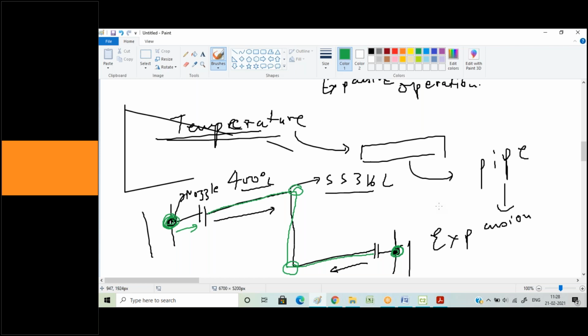There is no such thing there. For example, how much do you have to maintain the sustained sag? Because obviously, in the sustained condition, if I am doing stress analysis, first I want to see that displacement is controlled within 2.5 mm. Then only the pipe will be sitting on that support. Otherwise, it will not be useful for anything. So the first step is I need to control the displacement. For that, is there anything in B31.3? I'm asking especially.